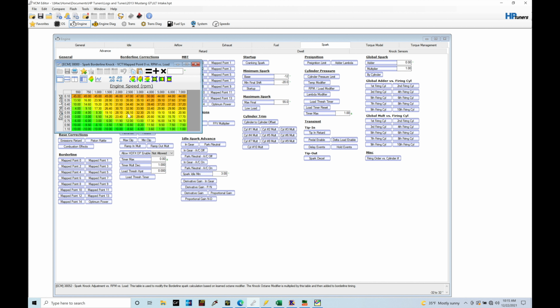And we'll find the piston's going to then change direction again. It's going to travel from that 360 degree marker in our crankshaft rotation, traveling downwards again to bottom dead center. At that point, the crankshaft at the bottom dead center mark on our power stroke, it'll be at 540.